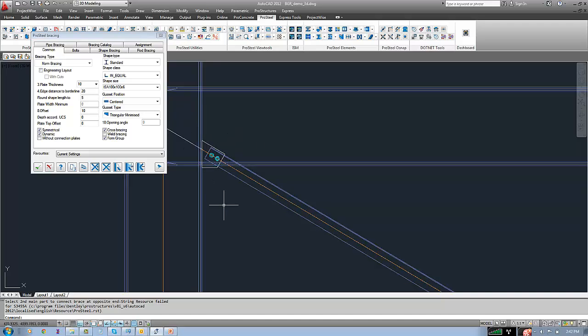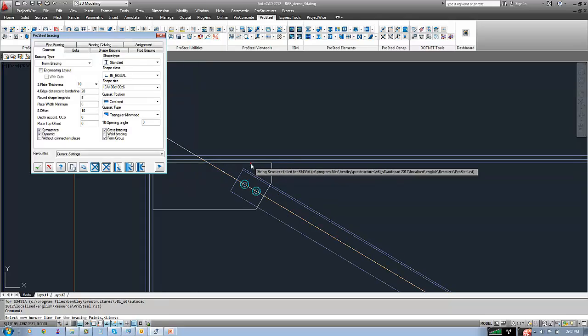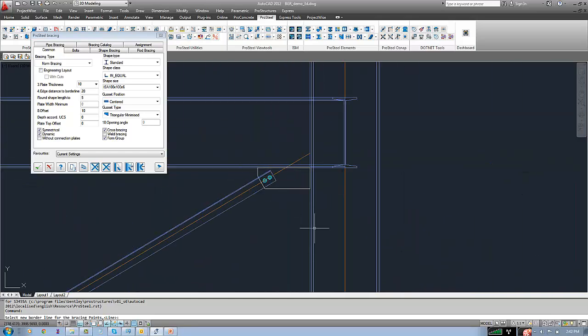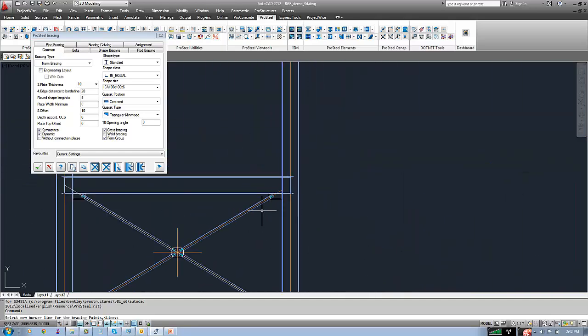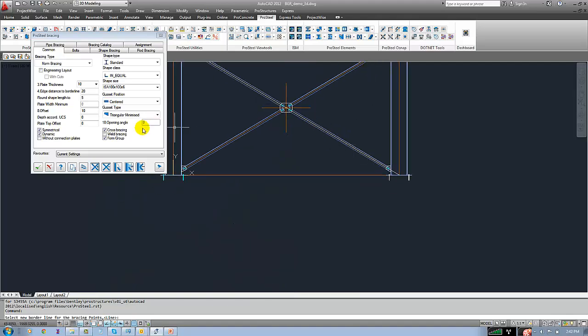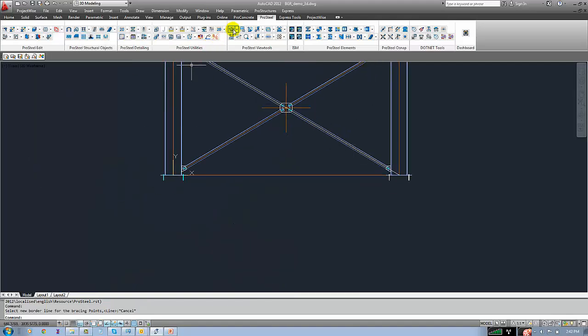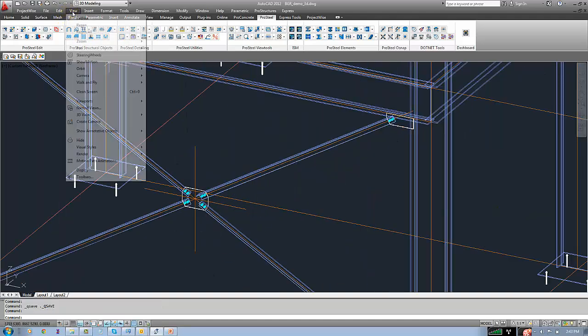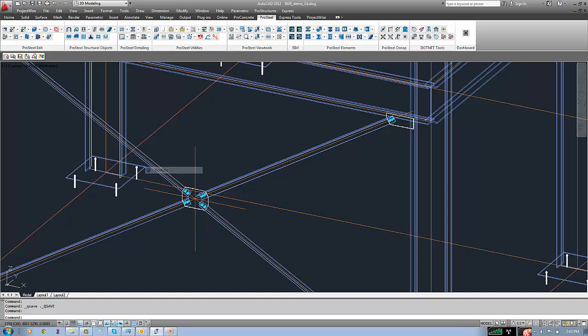So how will I take this one down? Here there is an option called add cutting edges. I will select the bottom line of the beam. Automatically it will adjust as per the beam positions. Okay. Now once I did this, let me take you to the isometric mode, and I would like to render the model.